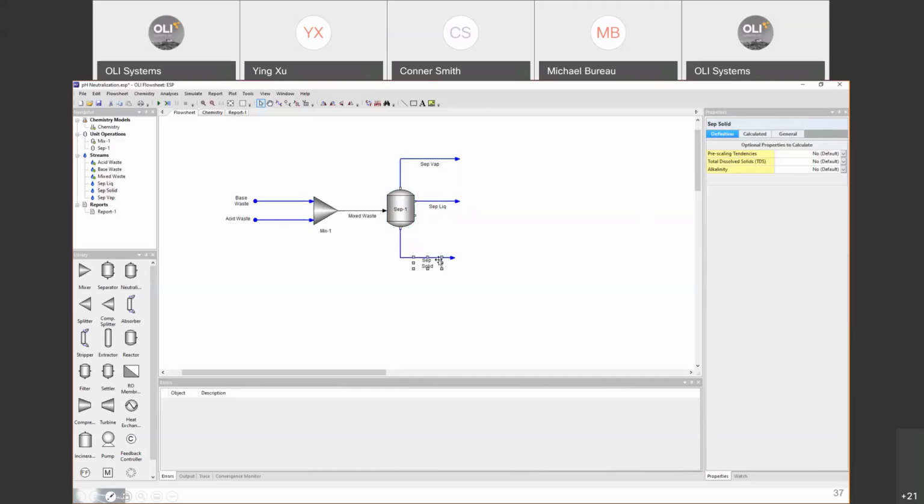So this entrainment option, I got out of it. That entrainment option will allow us to enter that information here. Okay, so if you happen to know how many solids in grams per grams go to the liquid, you can enter it here. If you happen to know how much liquid you have in your vapor, then you enter it here, and things like that.